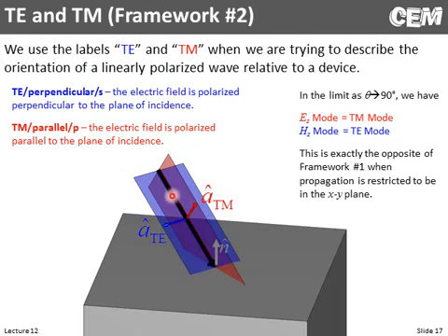As our wave vector comes in at 90 degrees and this plane lies down, so now our wave vector is in this plane. Well, there's a component pointing straight up now, which ends up being the TM mode. So when the electric field is pointing straight up, in this school of thought, you would call that the TM mode. This electric field would be within the plane, and in this case, you'd call that TE mode.